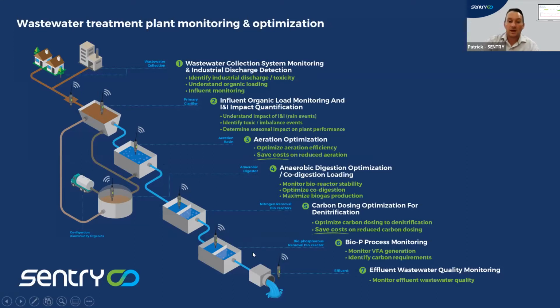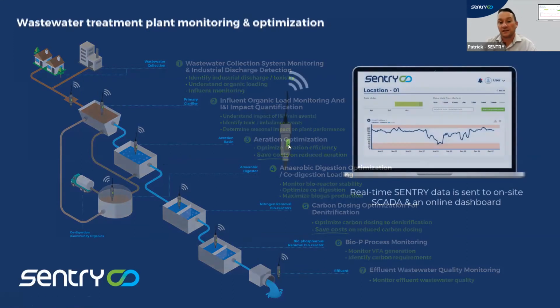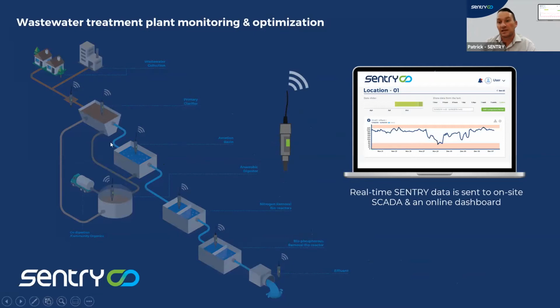The whole time, what we're providing is physical sensors that are just placed into the wastewater. You leave them alone. They're biofilm based. So we specifically ask, don't clean the sensors. We want people to inspect them every 3 months, but we don't want you scrubbing or cleaning the surface. And then that information is sent to the cloud, to a nice, clean, simple online dashboard, but also on-site, we can tie it via 4-20 into your on-site SCADA. All right, so that's the technology intro.